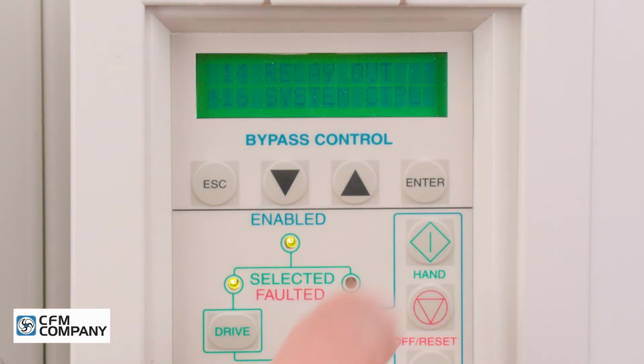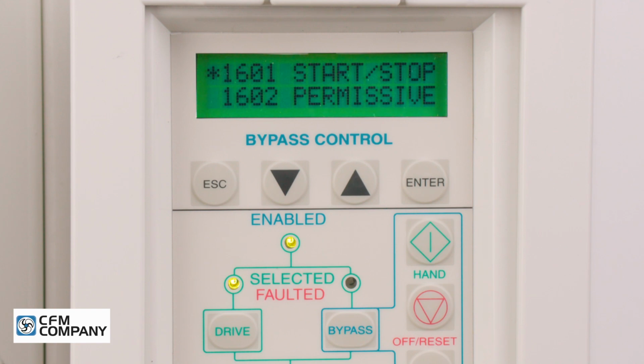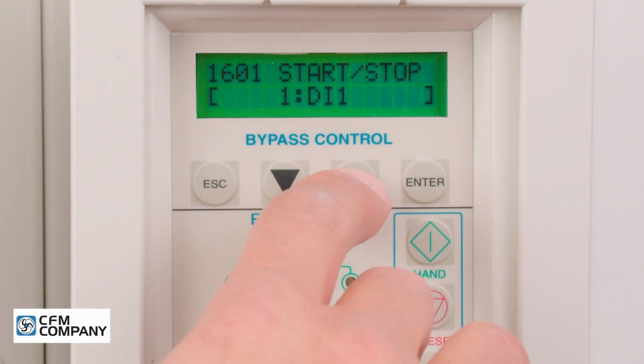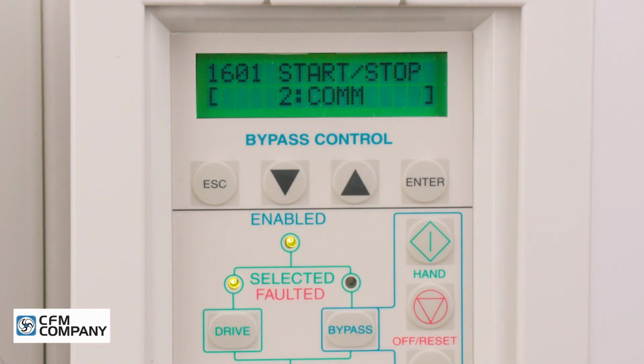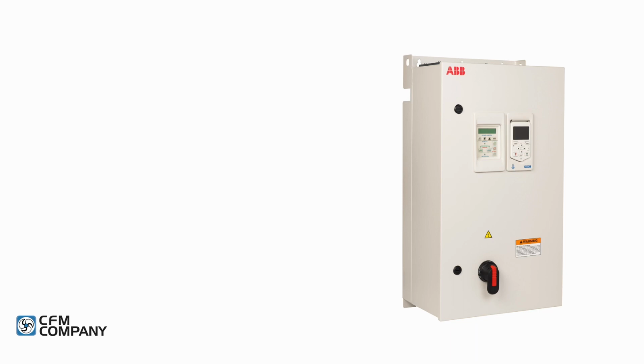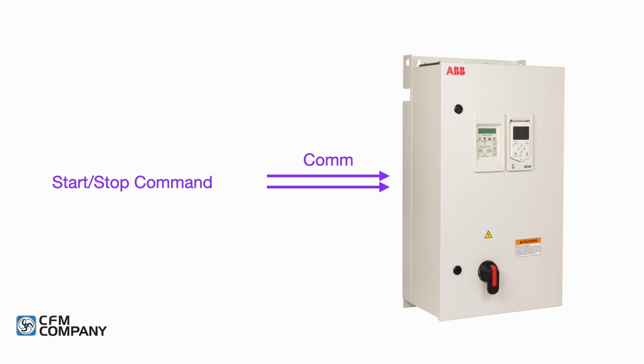Press Enter. 1601 Start-Stop is highlighted. Press Enter to edit. Use the up arrow and select 2 Comm. Press Enter to save. The drive and the Eclipse bypass are now programmed to receive a start-stop command using the embedded field bus, EFB.